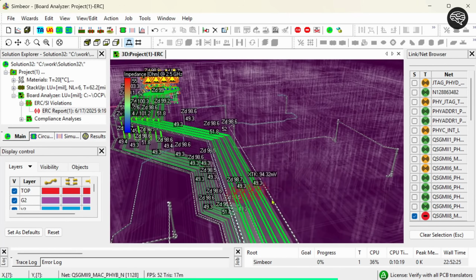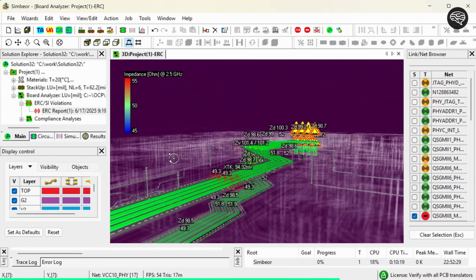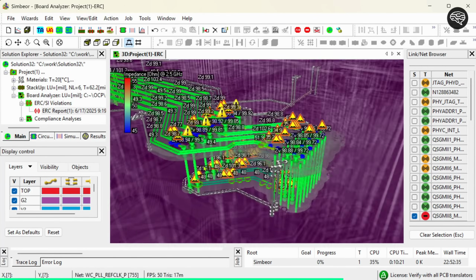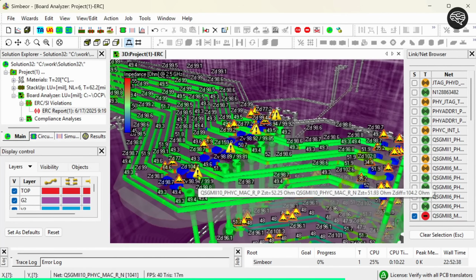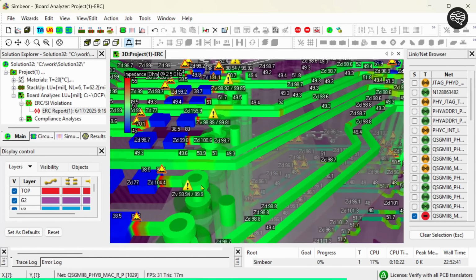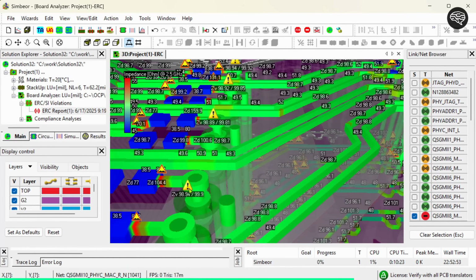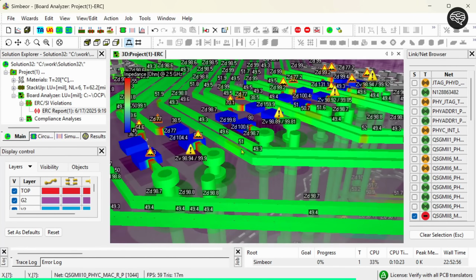That's crosstalk discovery, where it may come from, and the maximum value to expect at that location. The exclamation signs flag via holes, click 1 for details, via impedance from top and bottom, at which frequency, and the localization frequency, 16 GHz here. This one has just a single stitching via.